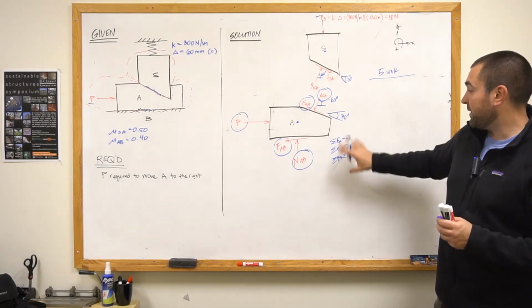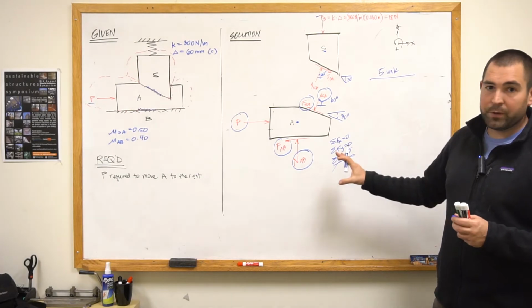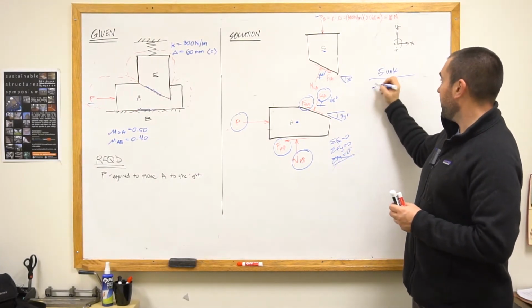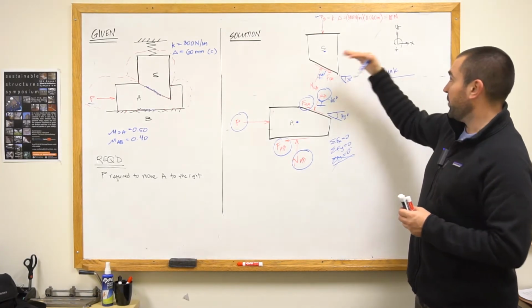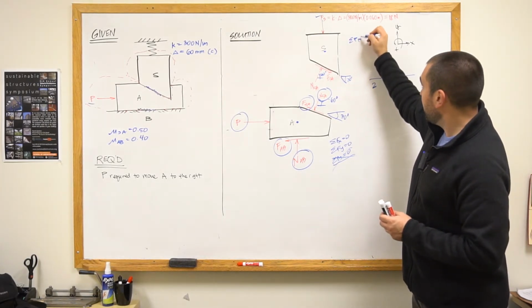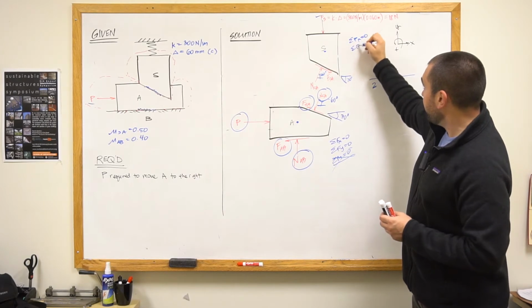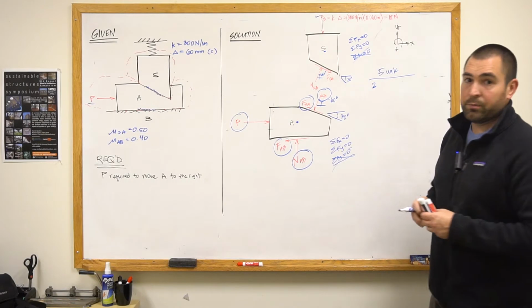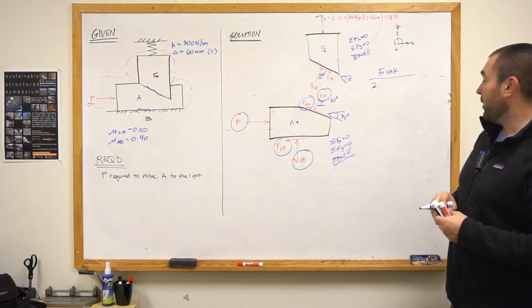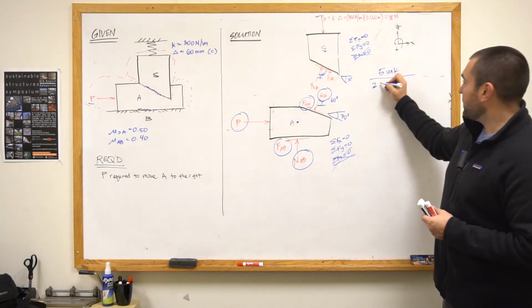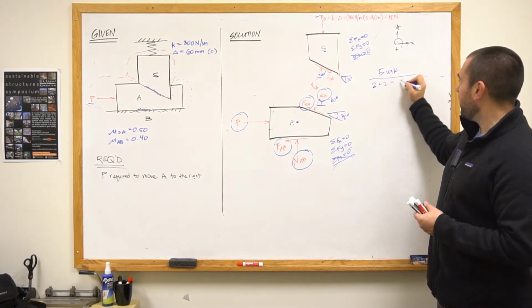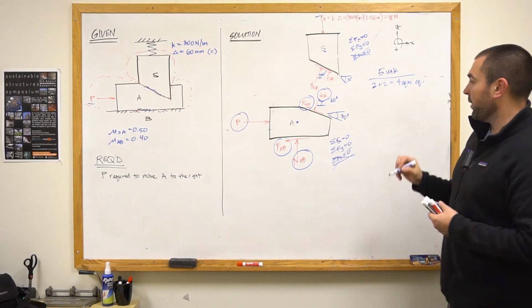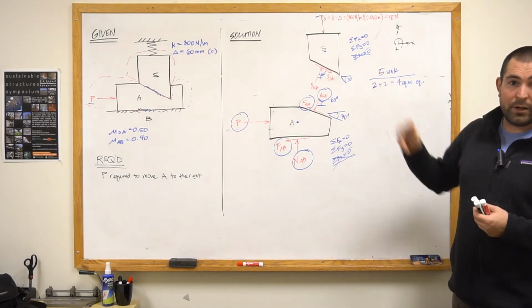So with the moment equation being trivial, what we're really talking about is 2 equations of equilibrium up top, just sum of the forces in the x equals 0, sum of the forces in the y equals 0, and again the sum of the moments is trivial because there's no dimensions given to be able to calculate a moment from. And so I get 2 from the top, I get 2 from the bottom, I get 4 equations of equilibrium, but again we said that we have 5 unknowns.